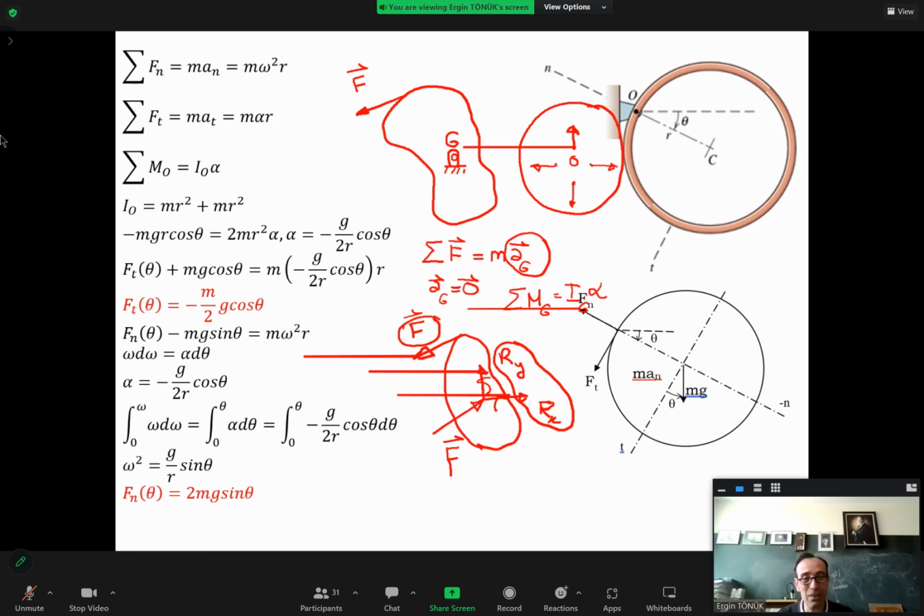Actually, there's another balancing. The car wheels are balanced in two planes. One is the external surface of the rim. The other one is the internal surface of the rim. Although you bring the mass center to the center of the axle, if it's a single plane balancing, which is what I'm explaining in the figure, you may have a shaking moment.